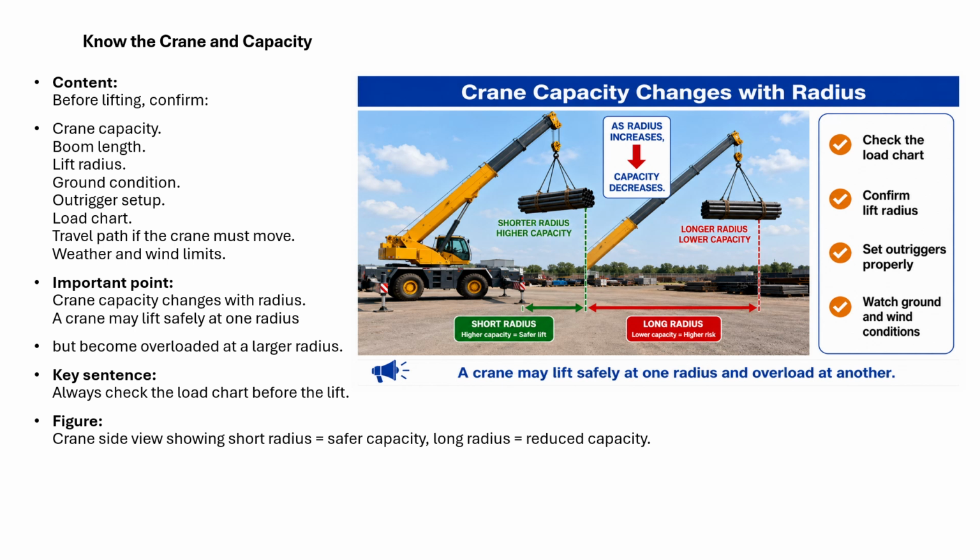Important point: crane capacity changes with radius. A crane may lift safely at one radius, but become overloaded at a larger radius. Key sentence: always check the load chart before the lift.